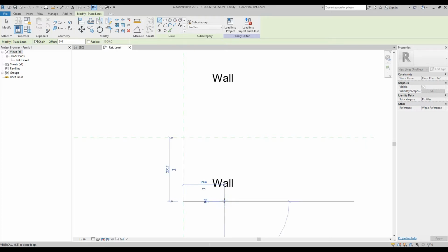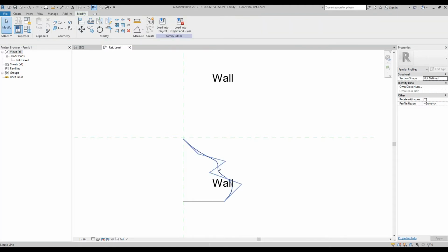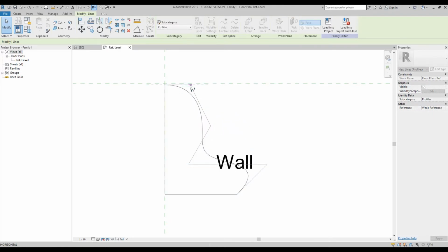Around about 130 in. Then go up to your user interface and select the Spline tool, and then click here, then here, then here, and here. Then we'll finish it on our last intersection line here, and you'll notice that our tool has finished the chain. Now we're going to edit it a little bit. Press escape twice and select the spline line that we've just done. We can use the pull handles to make more of an elaborate design as per its period.